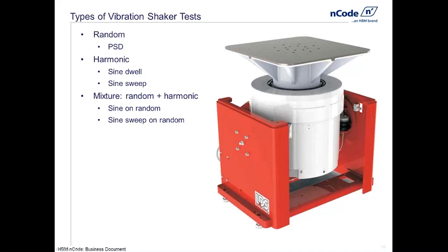So this is the shaker rig that may be in your test lab that is used to create inertial stresses in a part as part of a validation test. And the beauty of Design Life is that we can replicate this through the process I showed you at the very start of this presentation. We could call that process the virtual shaker table test, because we can have FEA plus Design Life working together to understand dynamic stresses and how those influence fatigue life.